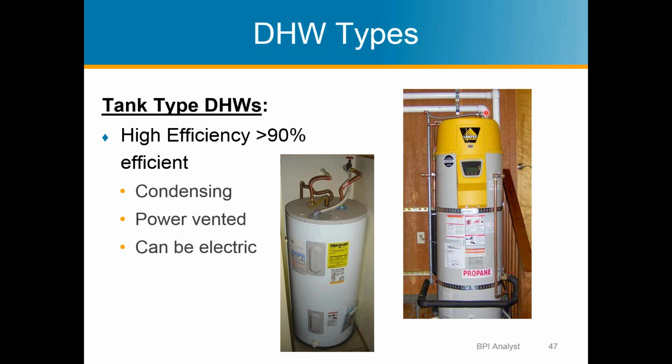They are power vented. You've got the same thing as your furnaces, where you've got the PVC pipes here as your exhaust, because you've taken all the heat out of the exhaust, so the exhaust temperature is very low, and the other one's going to be your air input, your combustion air going into the system.